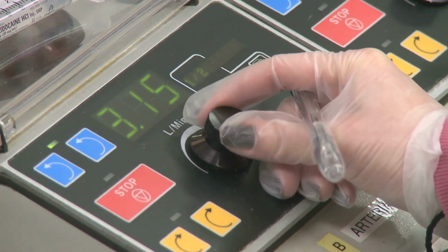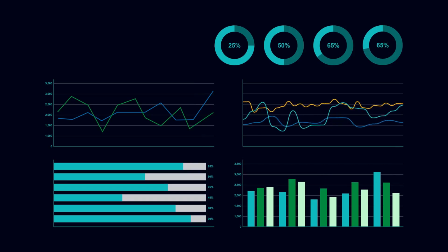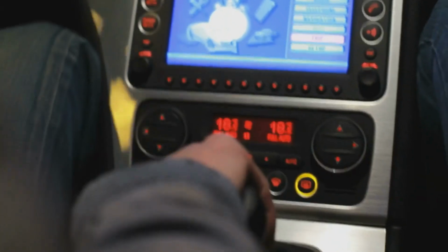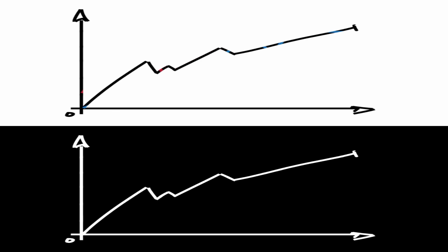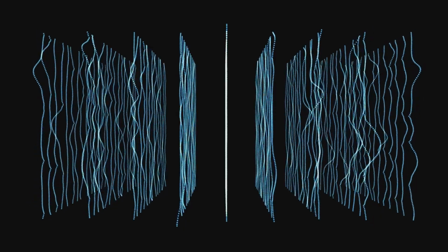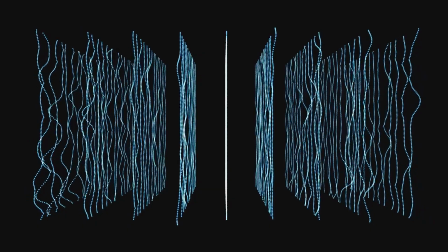With the proportional and integral gains set, we add derivative control to enhance responsiveness and stability. The derivative gain, or KD, influences how the controller reacts to the rate of change of the error. Start with a small KD value and gradually increase it while observing the system's behavior. The derivative term should help dampen oscillations and improve the system's response to sudden disturbances.